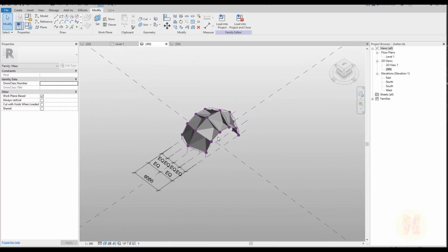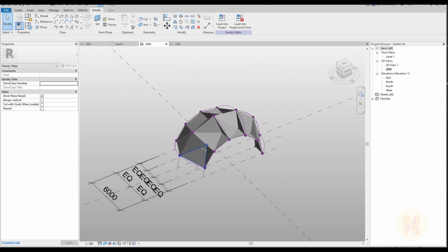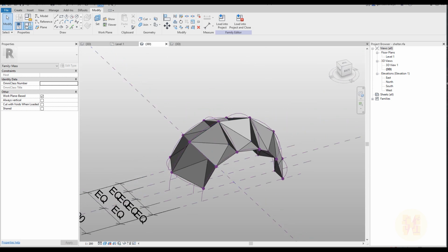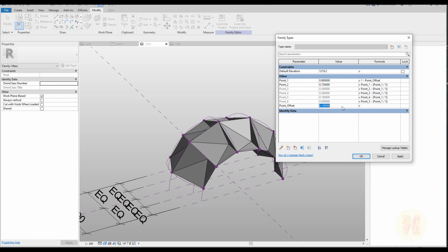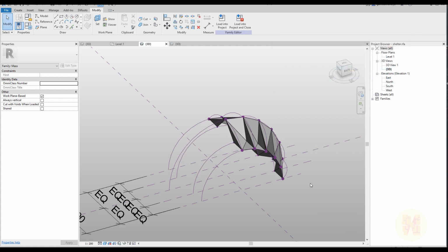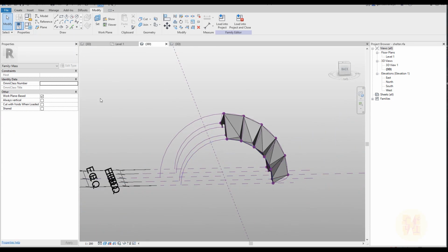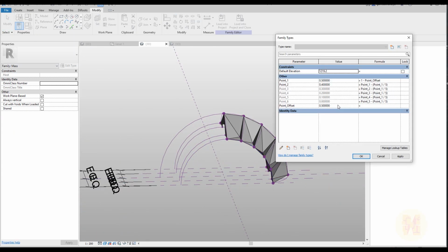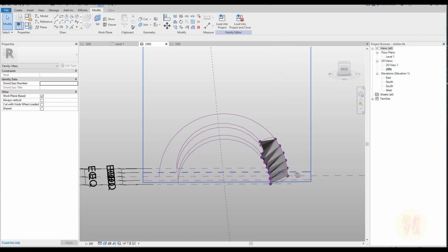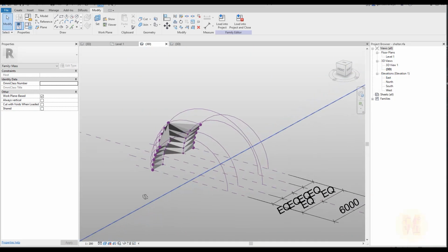And let's test it. So it's time to test. Now you should go back to your parameters, Family Types, and let's say here's this offset. So it means we will offset till the middle one. Let's say OK, and as you can see, the offset is working. Now till the middle one. Let's even do the stress test, as I said, 0.8. And as you can see, it's perfectly working.